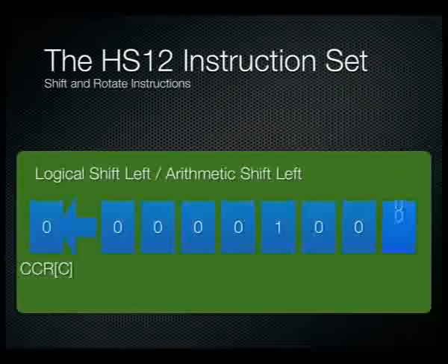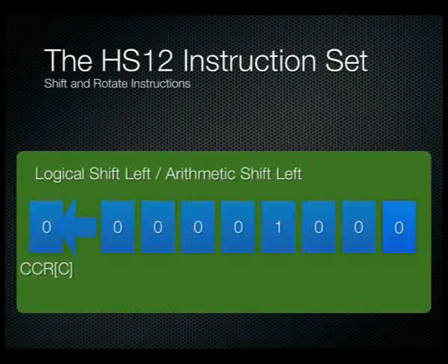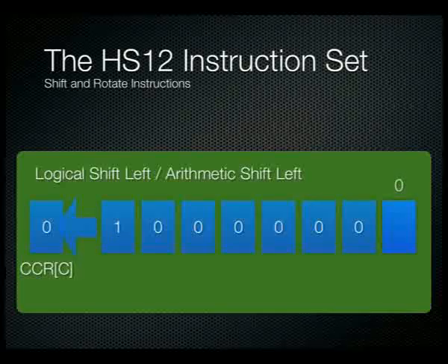Okay, so we can keep moving it, so we move it along left by 1 more, zero pad the least significant bit, the most significant bit moves into the carry, and we simply lose that value that's in the condition code register.